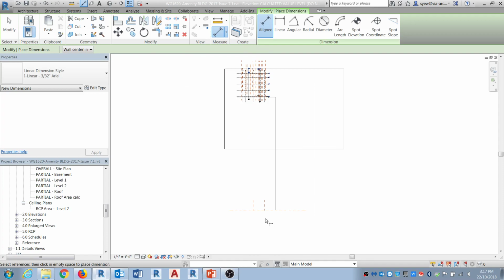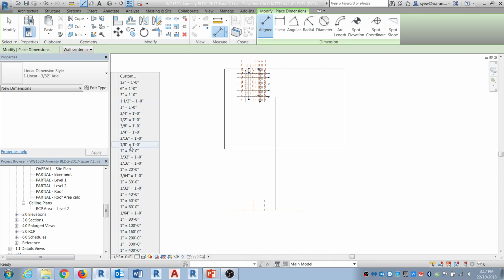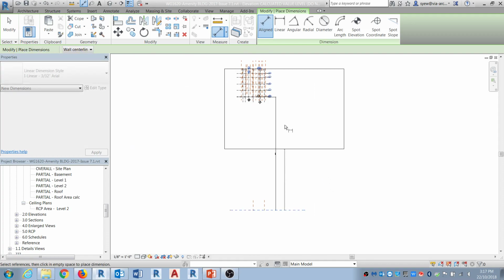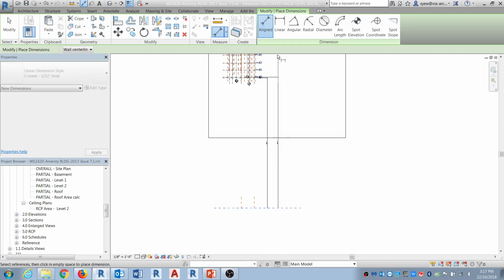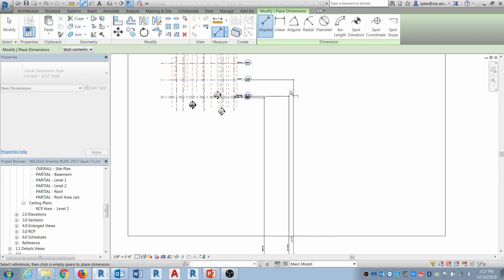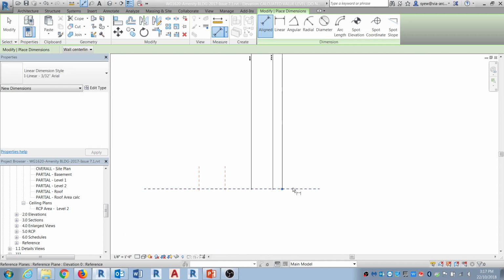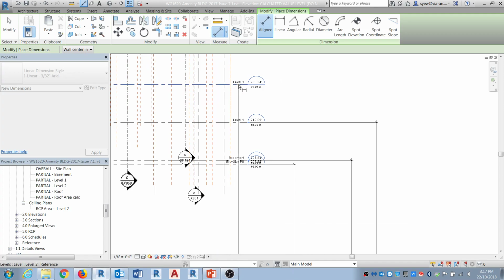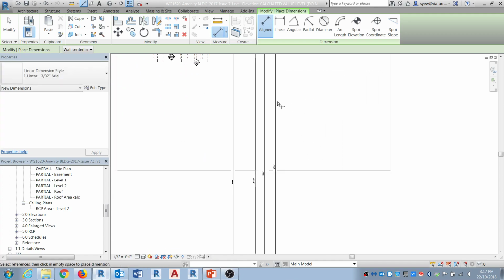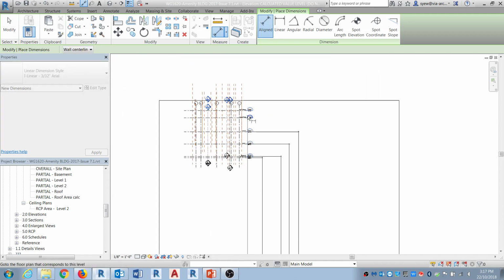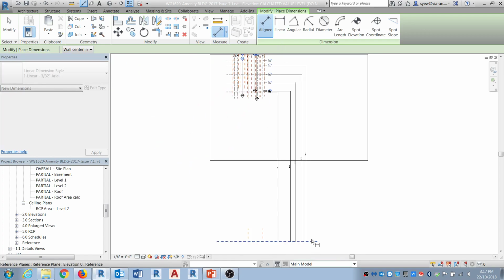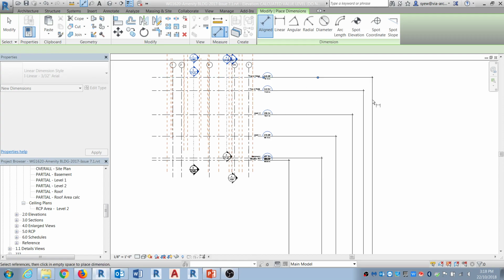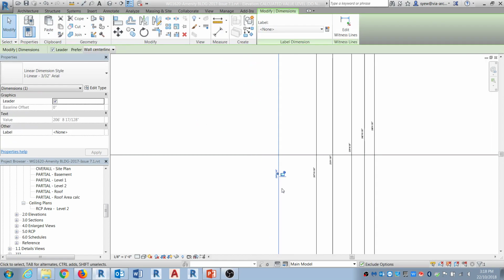Okay, I should probably make this a little bit larger. So let's say I'm going to go 1/8. Again, you're going to go 0 to basement, 0 to level 1, 0 to level 2. Let's assume that that's top of ridge, etc. Okay, so once you have that, the next thing you do is you want to click on this.